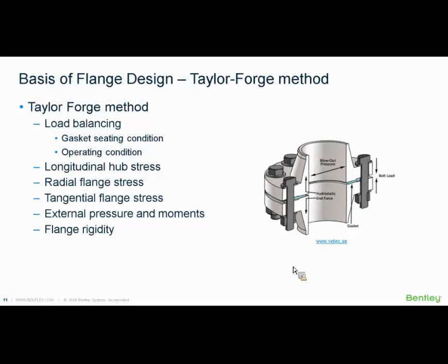The basis for the Taylor-Forge method. So the ASME flange design methods are generally based on the Taylor-Forge method, and this goes way back into the 40s and 50s, in which they actually came up with the initial design basis for the Taylor-Forge method. So the basic idea here is load balancing. For ASME flange design or the Taylor-Forge method, two different bolt loads are calculated separately for two different conditions.